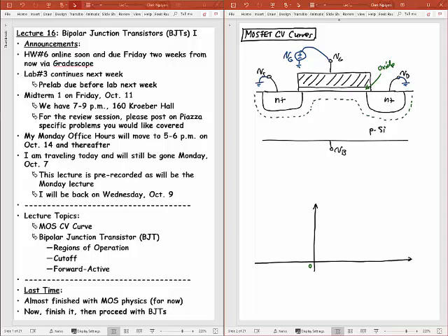underneath my channel, right? And so to create that depletion region, I'm basically pushing away holes from the surface near the gate, right? So as we talked about, you end up with negative static charge here. And so this negative static charge, it's charged there, but this is an insulator here. So in effect, if I were to think of the capacitance that I have, I kind of have a series combination between,